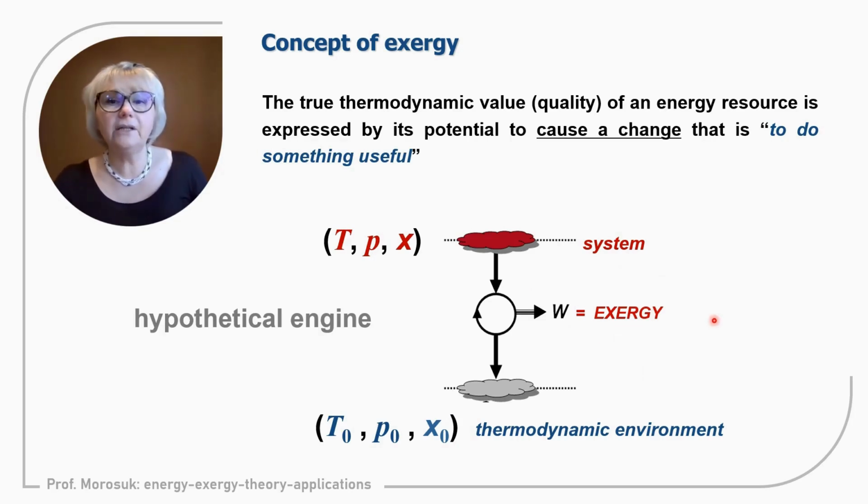So exergy and work are the same. All equations from thermodynamics that we know for calculating work under different conditions, we can use to calculate exergy. One more time, it is the concept of a hypothetical engine. No need to ask which process will take place, isothermic, isobaric, isochoric, and so on.